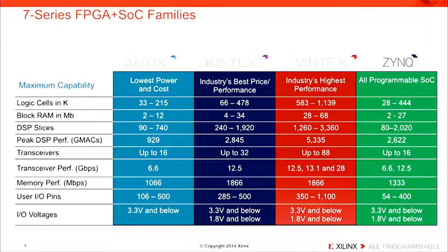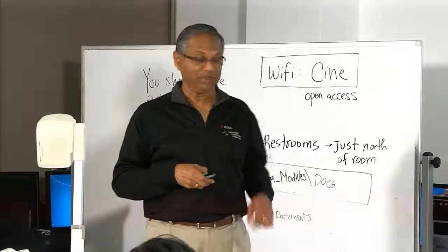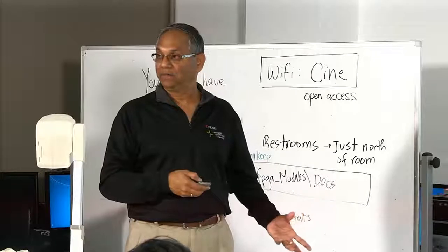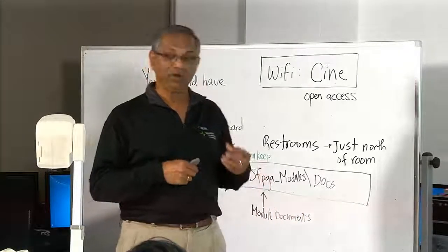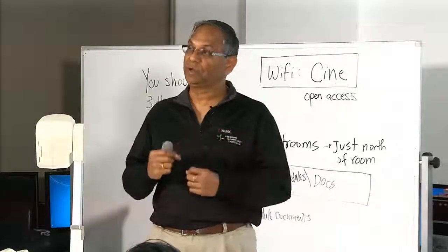And then of course Virtex is the highest performance device. And then Zynq is not going to have that many resources as the other subfamilies, simply because a portion of the design or silicon is used for Cortex A9 hard IPs. Okay. So you can do a lot of software implementation, and then where you need acceleration, you can move that acceleration into the programmable logic section.